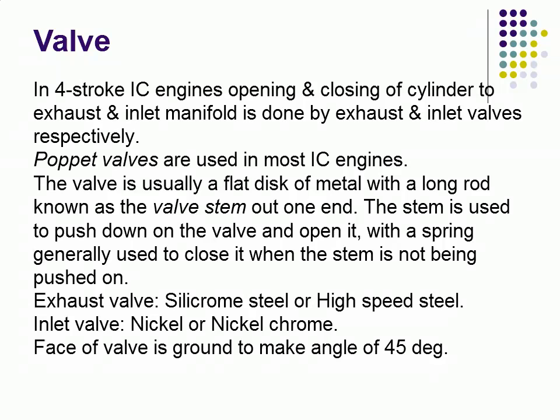The exhaust valve is made of silichrome steel or high-speed steel. The inlet valve is made of nickel or nickel chrome. Face of valve is ground to make an angle of 45 degree.